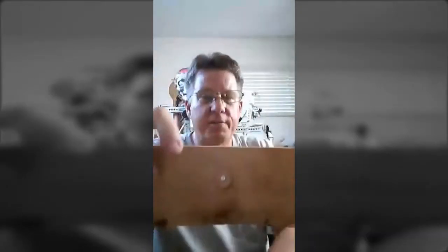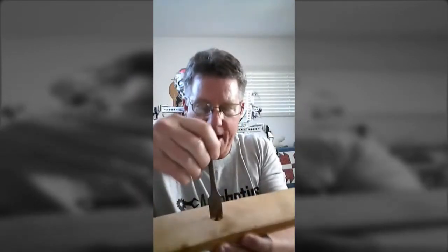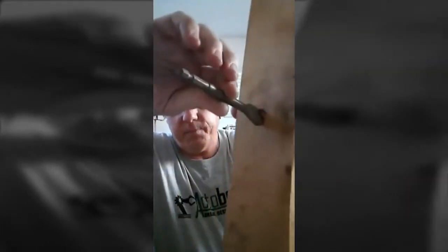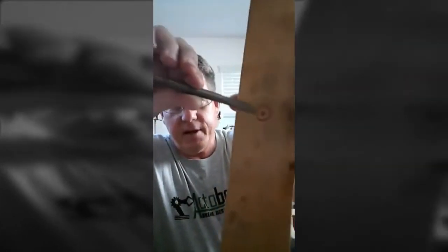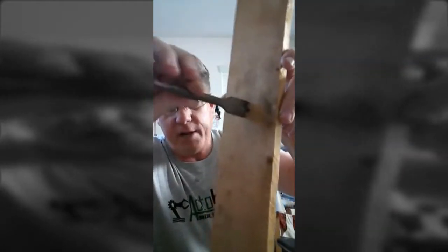What you do, I've got this block, and it's big enough that I can clamp it onto the base of my drill press. And what I've done is I've drilled a hole with a spade bit, and if you don't know what a spade bit is, it's a bit like this, and this is a 13/16 spade bit, and I've drilled about halfway down into this board. Okay, can everybody see that? And then, once you do this, you're just going to have a little triangular hole right in the center.